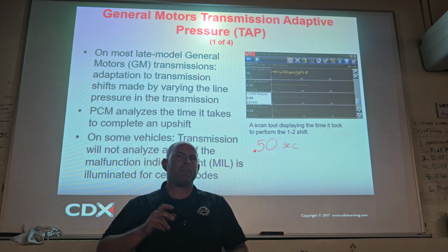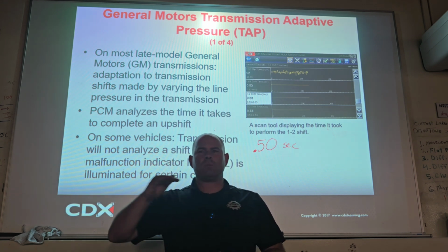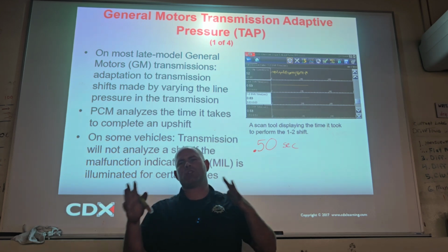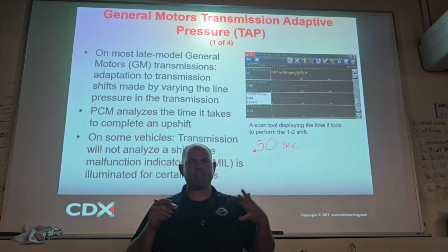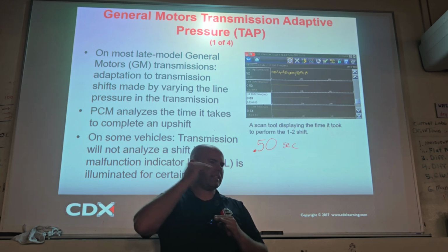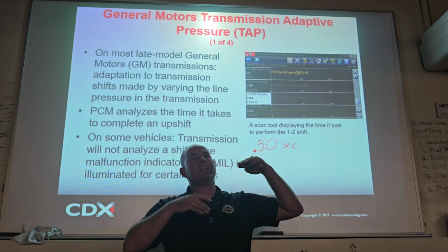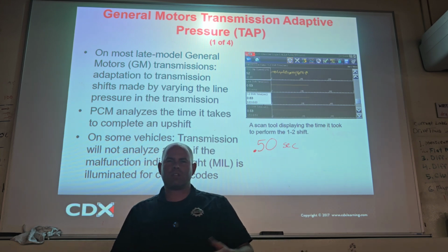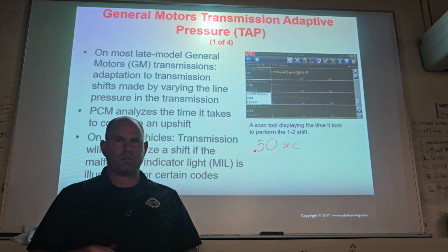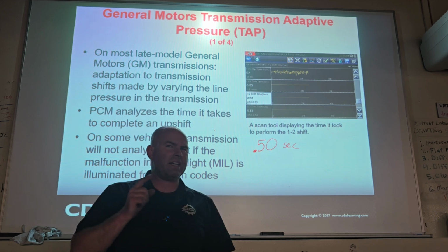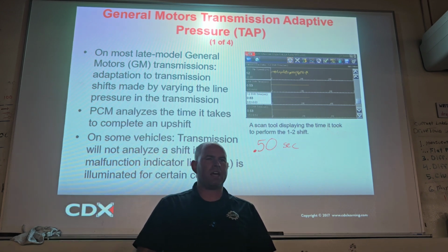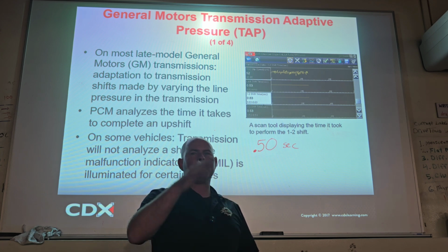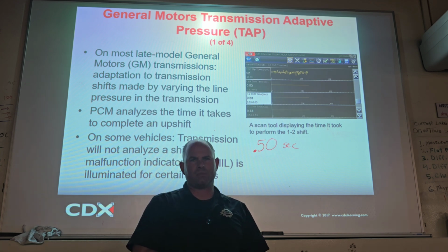It's going to be like shift delayed, but maximum pressure adapt value reached. Or it'll say something along the lines of maximum pressure adapt, but still slipping. So that's just saying it's adapted all the way and it still can't bring it in time. That's just a really good indication that the transmission is slowly but surely wearing. That's what kind of sucks about new transmissions: on an old transmission, you could feel it when it started to fail. On a new one, it'll just adapt so it feels perfect until bang, your light comes on.